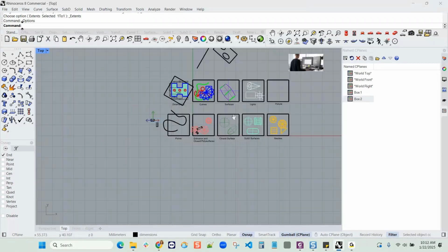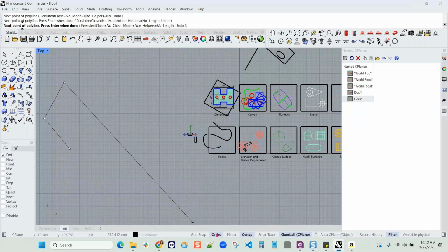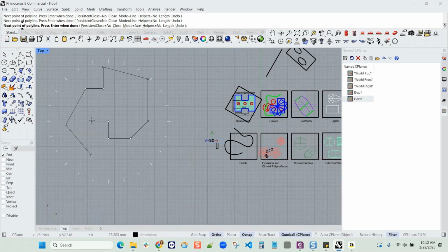So when you're drawing curves, so if I go over here and I pick a polyline curve and I start the polyline curve, I can really pick anywhere unless I turn Ortho on. And when I turn Ortho on, I'm restricted to whatever Ortho is set to. And in this case, we have 15 degrees, which is quite a lot. You might want some other feedback here as to what angle you're actually picking on.